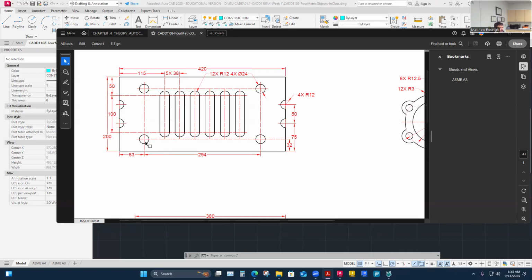If I were to check this as a checker, while I have that it's likely 32 down this way, and I can place this hole, a dimension that would be helpful would be the center to center spacing of the hole, especially on a really critically controlled part. Those hole pattern spaces might be really critical, and it could be that the outside edges of the part are less critical. We'll start to learn how to define the critical features of the part and what I can let run wild. By run wild, I mean it's less accurate.